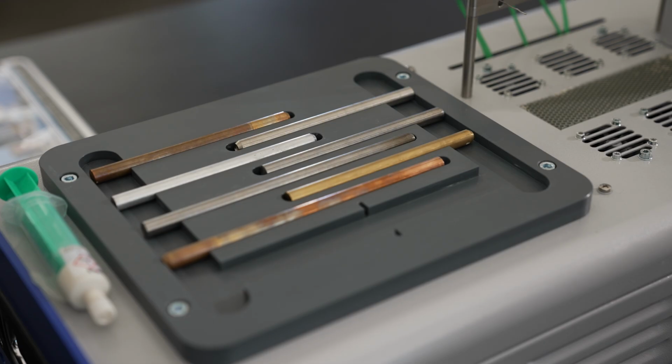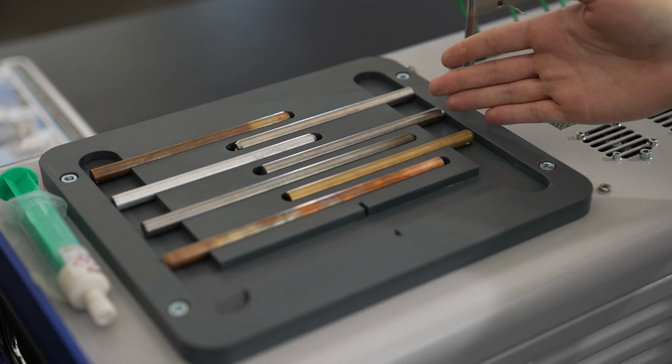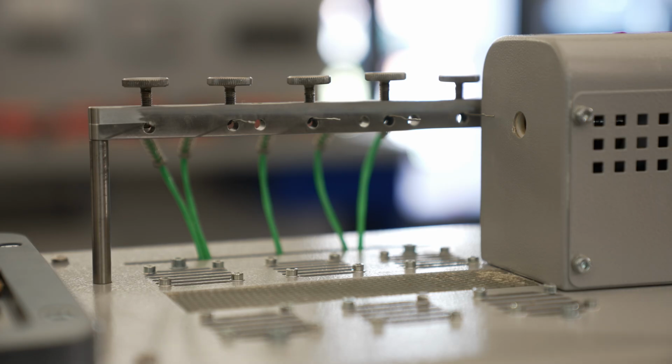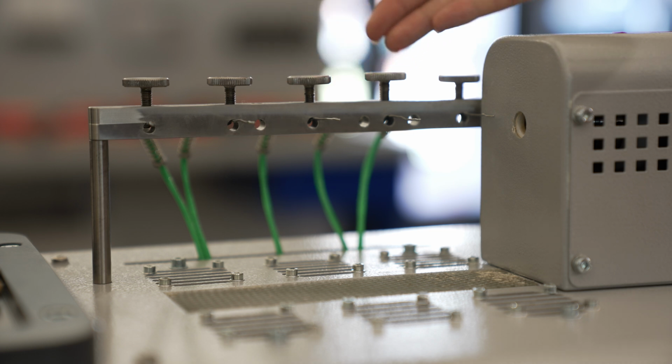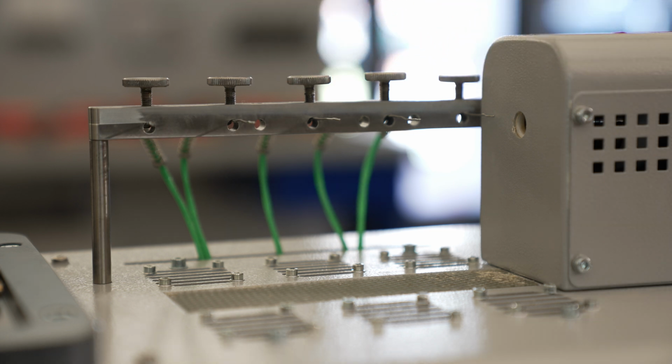The sample. 7 possible rod samples can be inserted into the heater housing port. The samples are of different length, called long and short, and materials, including aluminum, brass, copper, and steel. Temperature sensors. 5 thermocouples are to be placed inside designated holes in the sample to measure the temperature as a function of the sample's length. Refer to the laboratory guide for specific details about the sample and the location of each thermocouple.